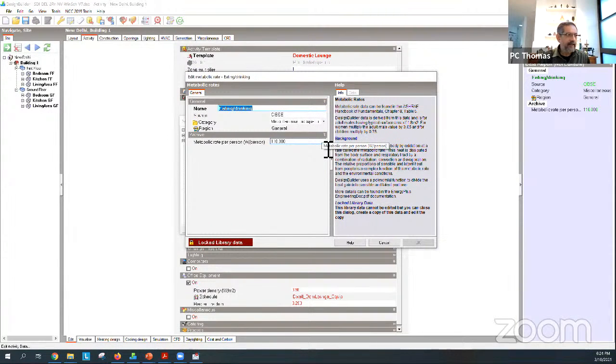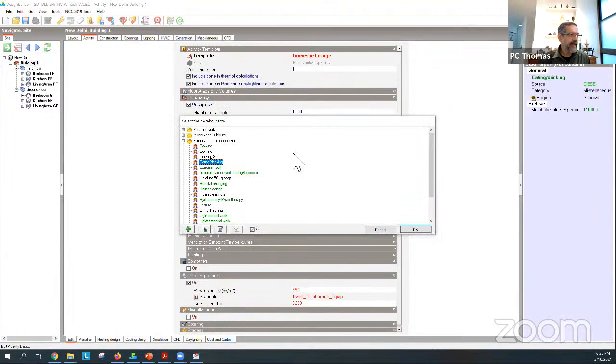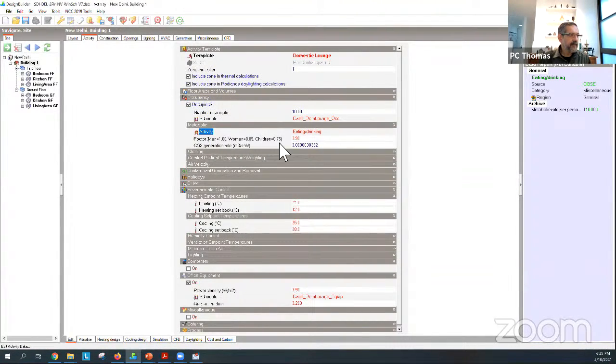Okay. Now, typically in Australia, if it's an office situation, we would use 130 watts for one adult male, and maybe slightly lower for an adult lady, and even slightly lower for a child, okay? And that's why you can see here that there is a factor for if you have an average of men, women, and children, what should be the factor?